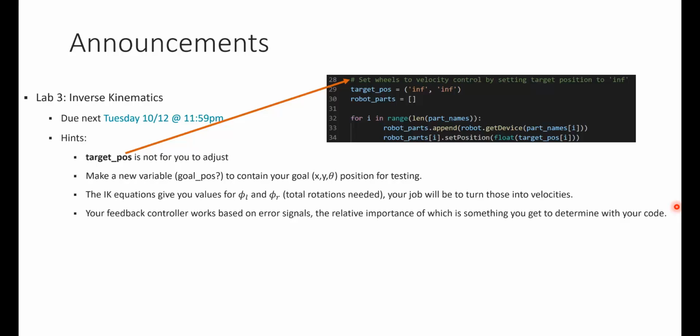One of the to-do items in the lab is to figure out values for x dot r and theta dot. In other words, the amount that your robot has to drive forward and the amount that your robot is going to need to turn. In the lab instructions, it tells you to set x dot r equal to something proportional to distance error, so you can just set x dot r equal to that. You can pick some kind of coefficient that reduces the importance of distance error, and your controller should still work. The idea here is that we're taking those actual sources of error, and then coming up with some determination of which ones are more or less important at any given moment. We'll come back to that in a couple of slides.